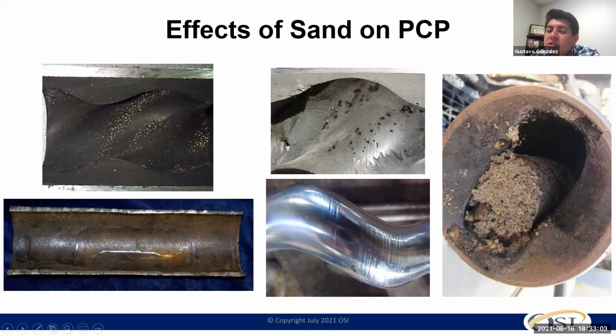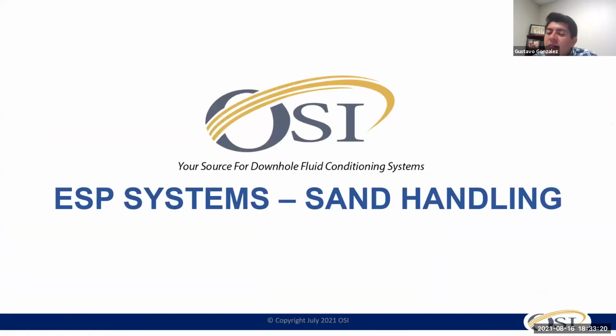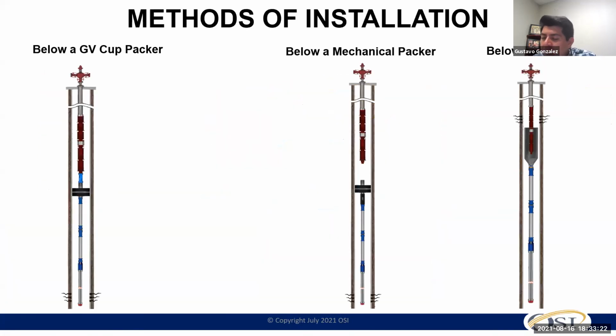So one of our approaches, instead of getting this chunk of sand going through your pump, is that there are multiple ways we can regulate and control the volume that is passing through, either per stroke or every single minute, through your system. What we normally do, there are different approaches, and again, it depends on the artificial lift. In the case of ESP, as you are aware, the intake of the ESP is on the side, as we saw in the previous picture.